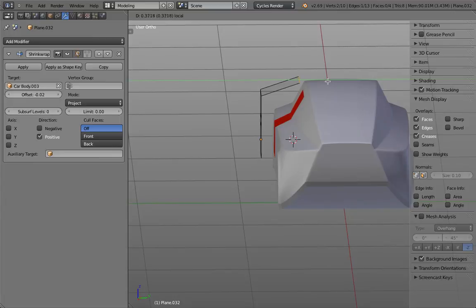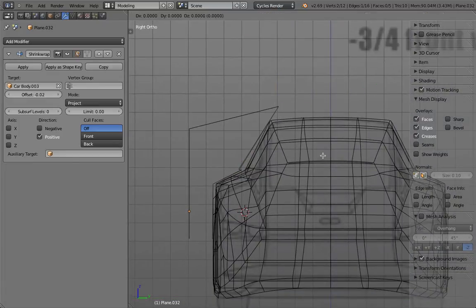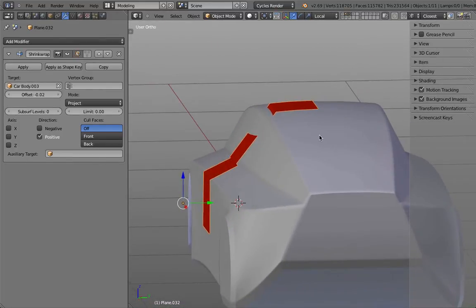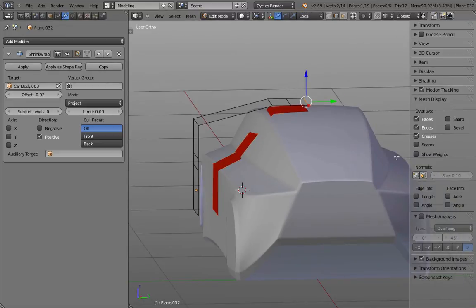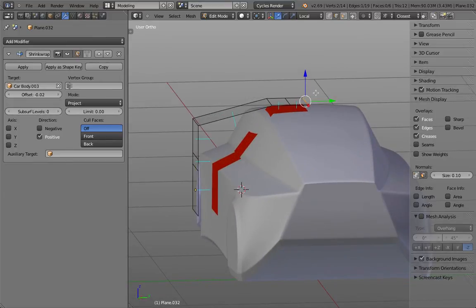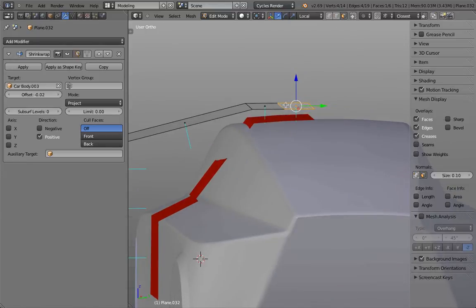So if I, for example, now move actually this point over to there and press Y and E and Y, you can see that I actually can make the surface follow it. And the main reason how this works is, again, the normals are the key. So you see each face has its normal, and whatever is below this normal, the surface is being projected onto.